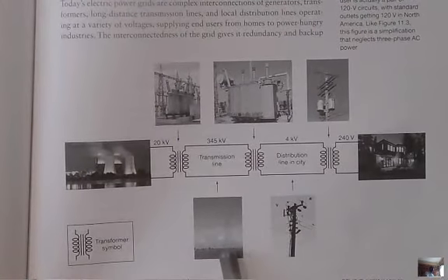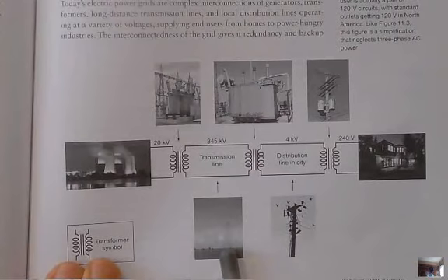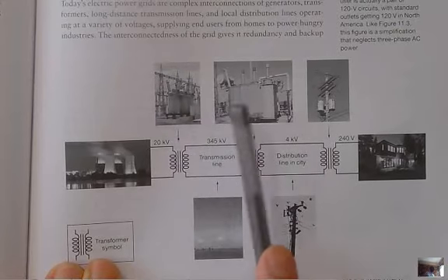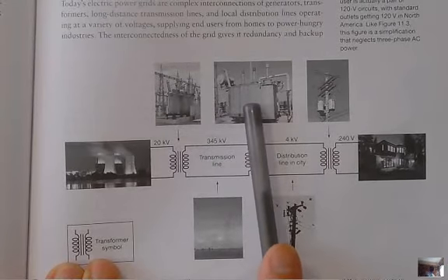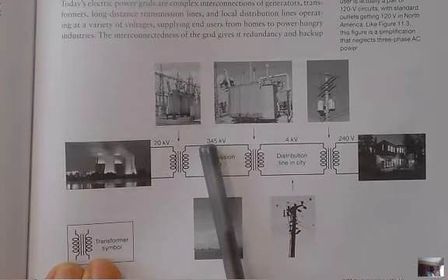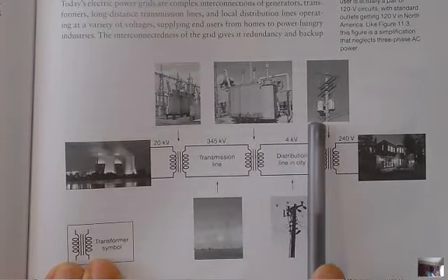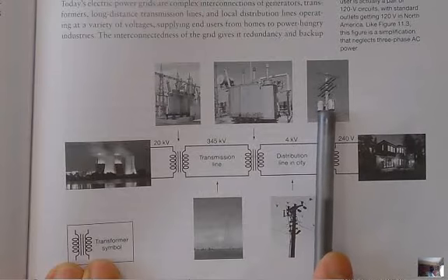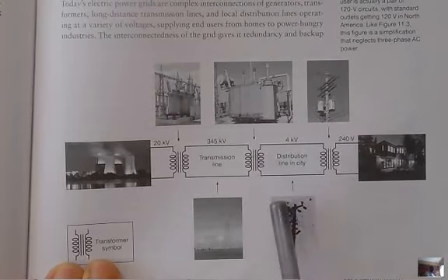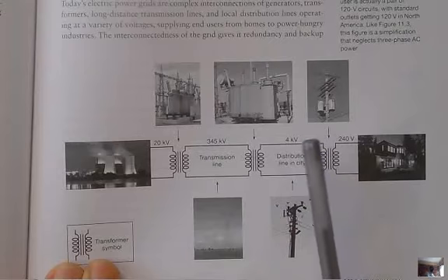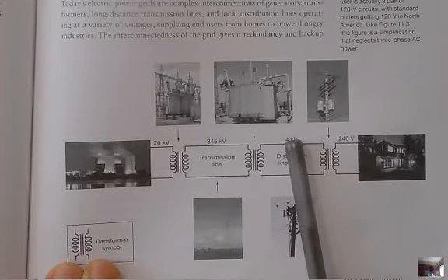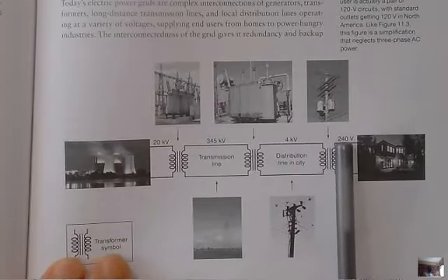Here's one of those high voltage power lines that you see leave the power plants. Usually nobody has their house directly underneath it. There's a byway there, and it's just fields where people walk their dogs and stuff like that. Then here's the substation in your town, which takes it from 345 kilovolts down to 4 kilovolts. And again, this is what it looks like at your telephone pole. The job of your telephone pole is to bring it from 4 kilovolts down to the 240 that's coming into your house.